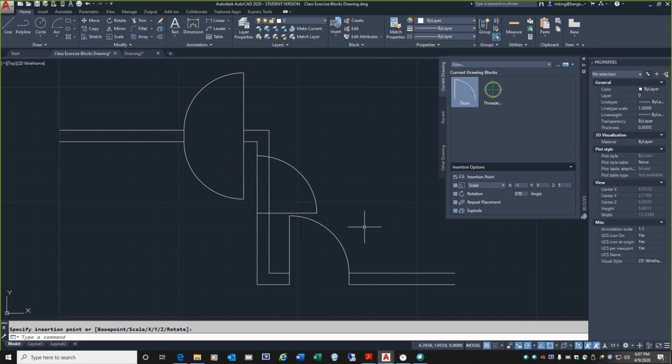Okay? So when you do this a lot, I struggle a little bit because I haven't done this in a while, but when you're in a floor plan and you have one block, trust me, after you do it a couple of times, you'll know before you even think about it. But again, what does this do? It saves me from having to create multiple blocks in different orientations. And that's the name of the game, is to keep your symbol library as small as possible, so that it's manageable. All right. So I wanted to show you this, the ability to use almost a mirror and a rotate mirror by throwing in negatives to the values here, and getting even more flexibility out of your blocks.